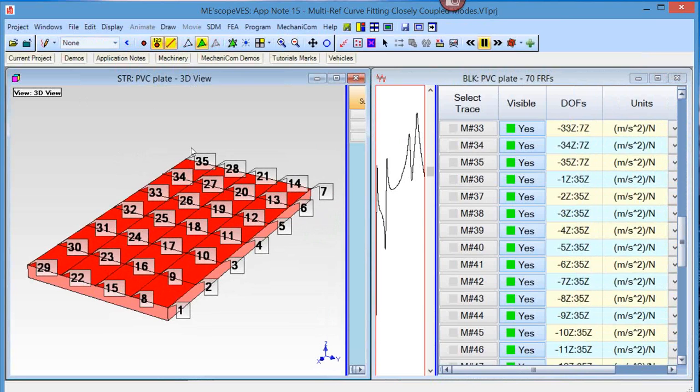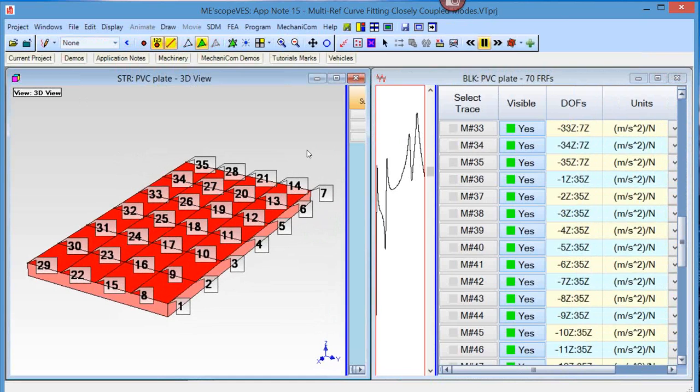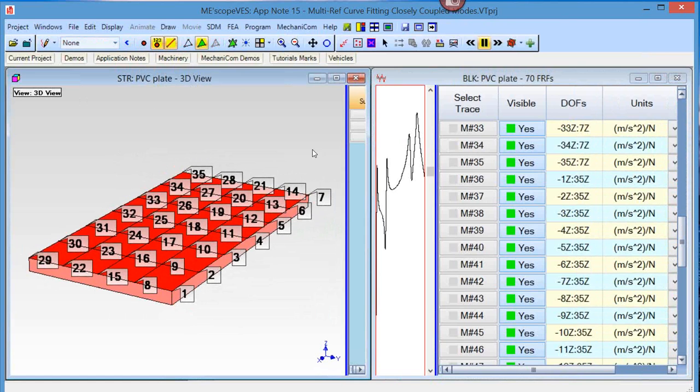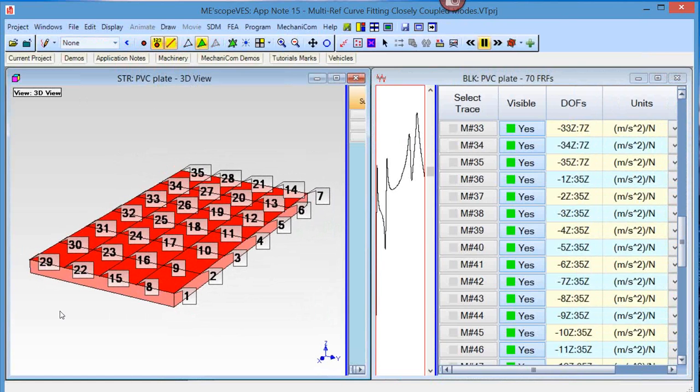Now, Z in this case is the actual Z as defined at each of the points. So those are what we call measurement coordinates, and each point has its own measurement axes or coordinates, not necessarily the XYZ down here in the lower right corner of the graphics. Those are called global. Anyway, let's go ahead and start the animation here.